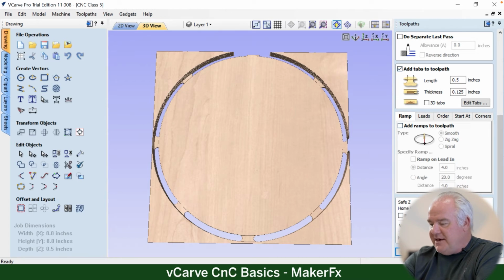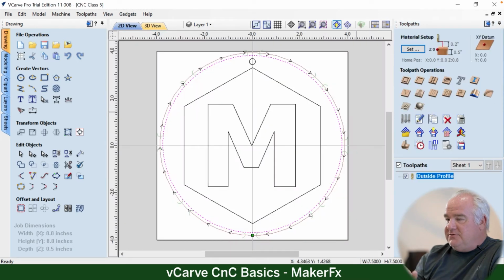And sometimes you'll do that. You'll experiment with some different things, but you always want to click on calculate. The most common types of end mills that we're going to use are, both of them will have a 1/4 inch shank. Those are the most common, but the actual cutting end of that will either be also a 1/4 inch or an 1/8 inch. But they make different sizes of shanks, but those are the two most common ones that you can use.